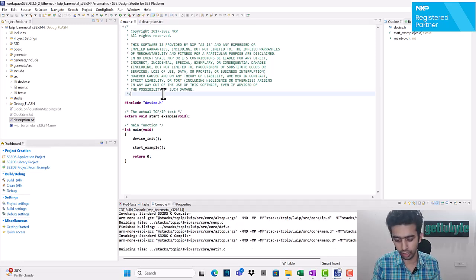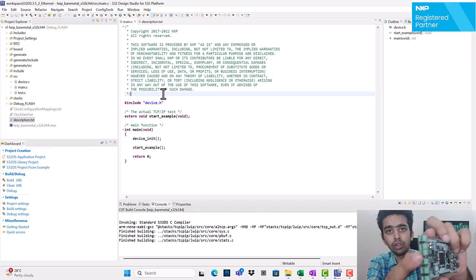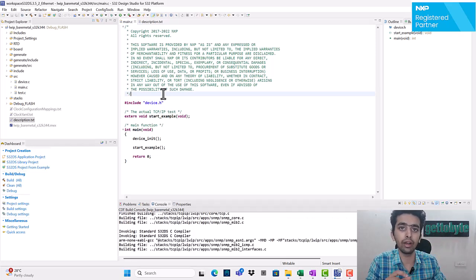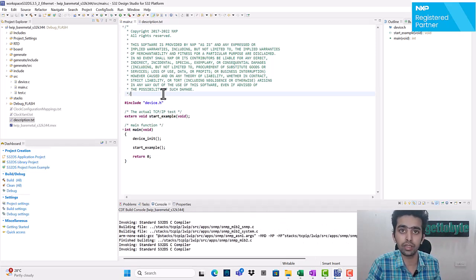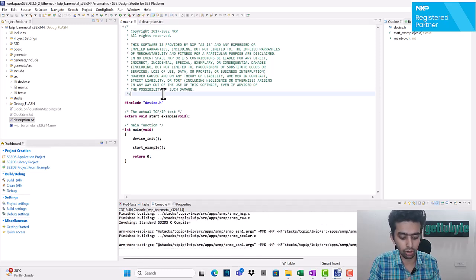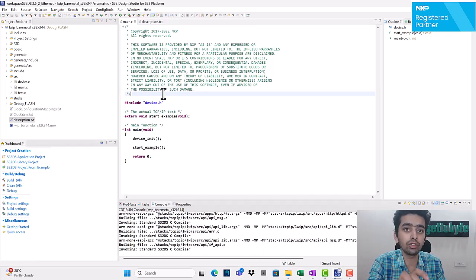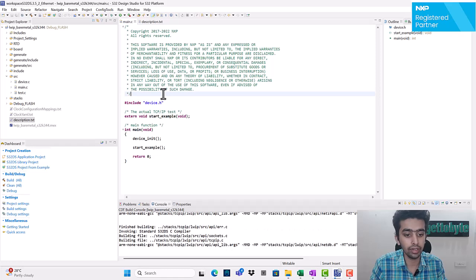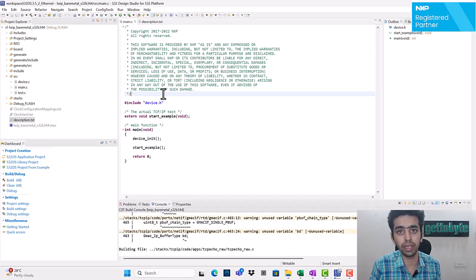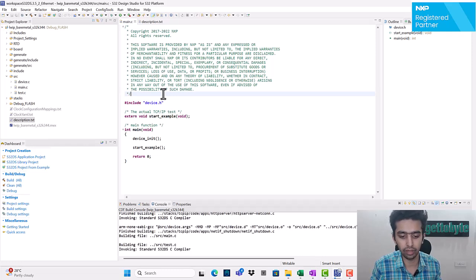We will now connect our Autoboard version 1 board from the Ethernet terminals to the Ethernet media converter, and from that Ethernet media converter to the PC via the RJ45 Ethernet connecting cable, so as to have automotive Ethernet communication with the PC, which uses standard Ethernet. Then we will run this LwIP ping example that we have just built and compiled.